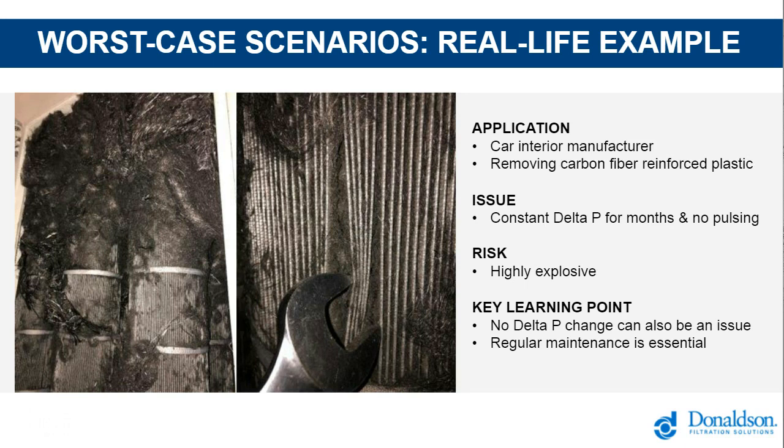So by opening up the dust collecting system, you could see the full accumulation of these dust fibers. So really a dangerous situation, highly explosive. So the message here is that also no indicators can mean something. Our intention here really is to make you aware that not doing proper maintenance can come with high risks and associated high costs.